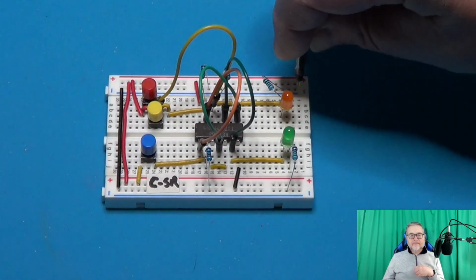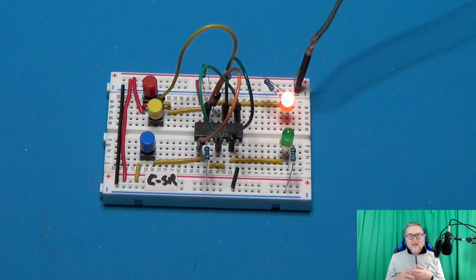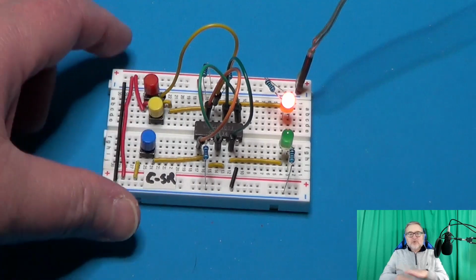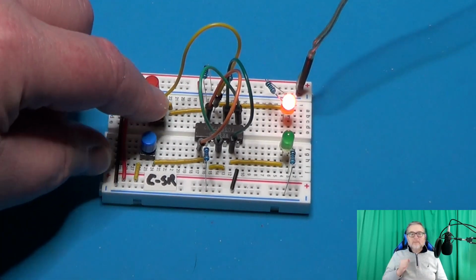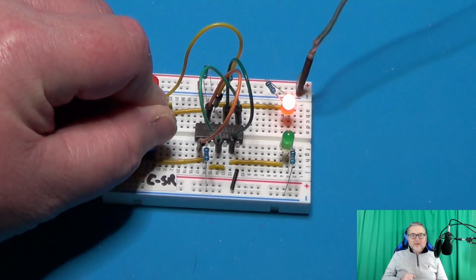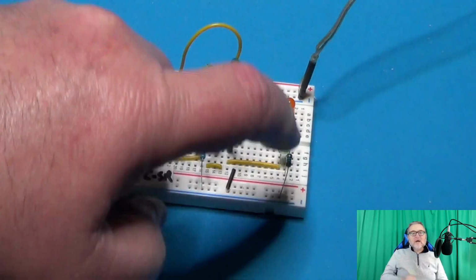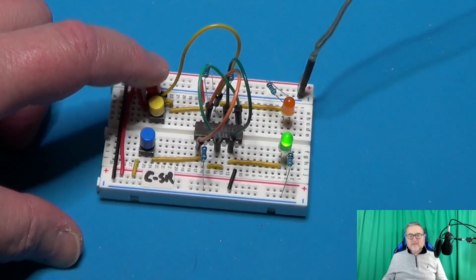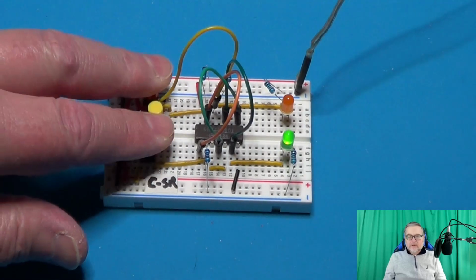Let's power up. And right now we have the Q output set to 1, and whenever I push the set or reset buttons, this state does not change, as expected. But now, if I push the clock button and the reset button at the same time, the flip-flop changes state and the inverted output goes to 1. Once the clock is 0 again, whatever I do now does not change the state any further.